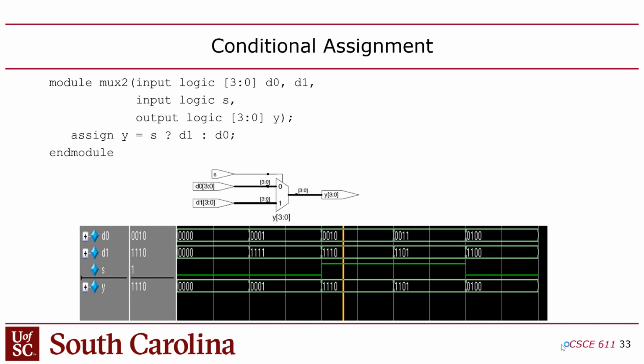And by the way, this is basically how FPGAs work internally, because in an FPGA, you put all the logic gates down, and you do that just by writing a RAM. Every logic gate is created as a RAM because a logic gate is a truth table, and a truth table is just a RAM. It's just a table. A memory is a table, a truth table is a table. So by setting up tables, small tables called LUTs, you can create configurable logic gates, right? But the real magic of an FPGA is not the LUTs, it's the fabric, the wires. How do you connect the LUTs in an arbitrary pattern?